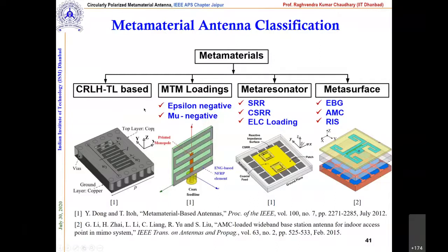Why is this important? First, we should know the conditions: it has two orthogonal components, the magnitudes should be the same, and it should have a time phase difference of odd multiples of 90 degrees. This is the condition that must be managed in the structure. And what it provides is higher link reliability, and immunity from Faraday's effect,